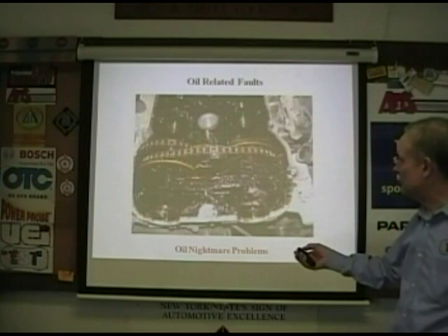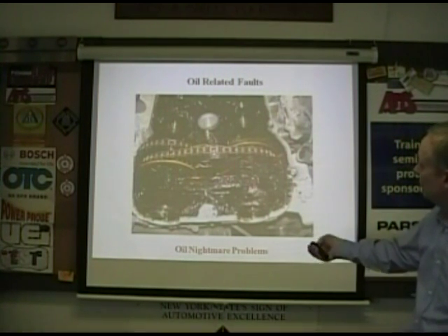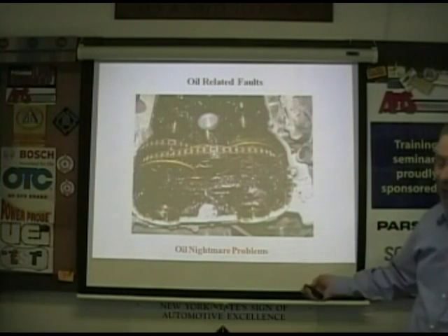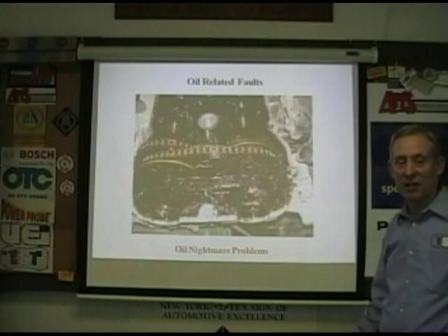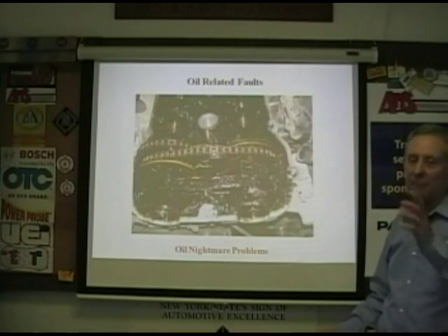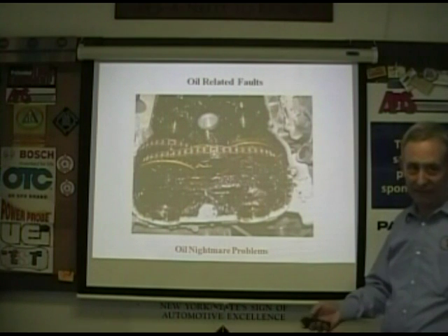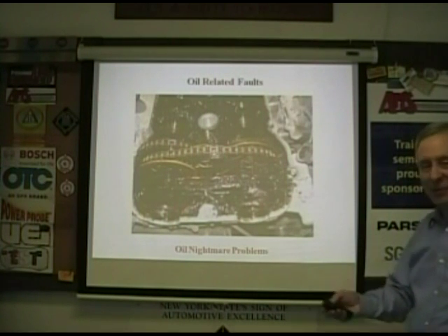Earlier generations than this had a different layout inside the Vanos. It would chatter and it would actually cause the timing retard, the knock sensor would hear it and pull back timing till the car ran like a total pig. That's similar to the Porsche setup as well. Right. Yeah, they all went to the same university.